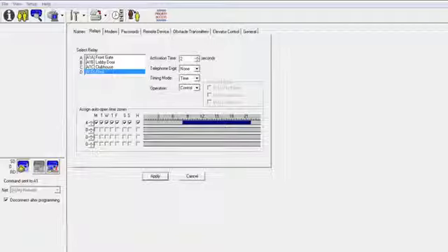Finally, if we're not already communicating with the node, we need to go online and upload. Once the upload is complete, the icon will be grayed out and a 0 will be displayed next to the On/Offline with Installation icon. By placing a checkmark in the Disconnect After Programming box, AccessBase 2000 will automatically disconnect from the panel after programming is complete. If the box is not selected, AccessBase 2000 will stay online until a manual disconnect is performed or AccessBase 2000 is closed.